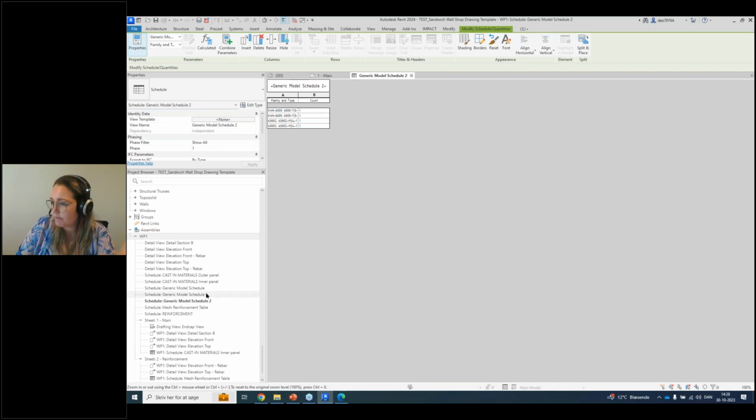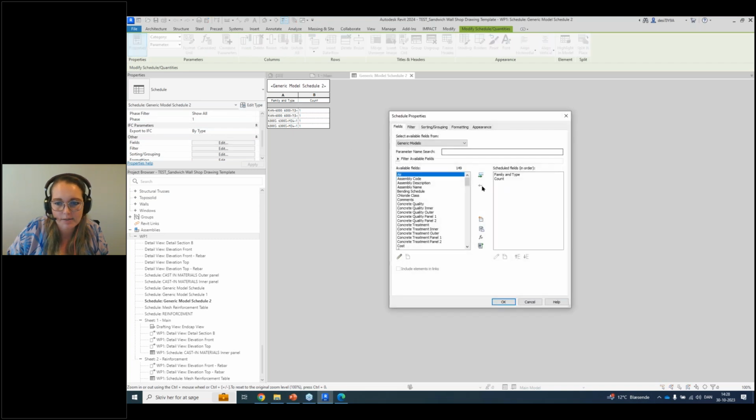Now this is a Revit functionality, and for you that are experienced Revit users, not something new. For you that haven't been doing that, well, there's plenty of information out there. So I'm not going to use time setting up a schedule. Basically what you need to do is go in fields and add parameters.